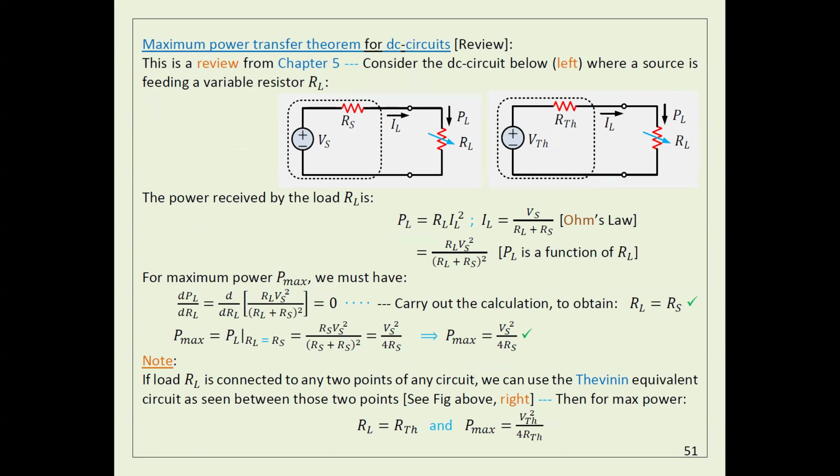This is completely different from DC circuits. So again, in an AC circuit, for power, we have 2 types of power. We have active power, which is good, and reactive power, which is bad, because it increases the losses. And we have something we call the power factor. If I can bring the power factor to 1, that means you can minimize the losses, which is good, and maximize the active power, because it's a useful power.